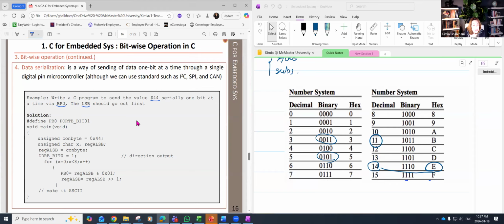How do I do it? Again, I'm going to first define my variables, whatever could be the name in here. It was asking me, you want it to be 44. That's why I said, okay, I'm going to use A0 to transfer the 8 bit. And then if I want to send the 44, I have to say 0x44. And then I need you to understand what is 0x44. Simply means convert it to binary equivalent.